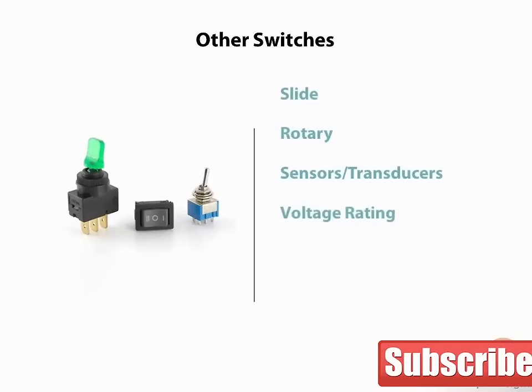In selecting switches, always observe the switch's maximum voltage and current rating, and stay well below it to make sure the switch is not electrically overloaded.